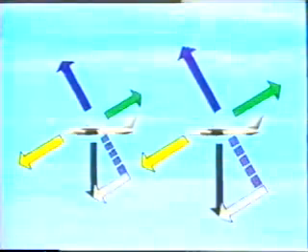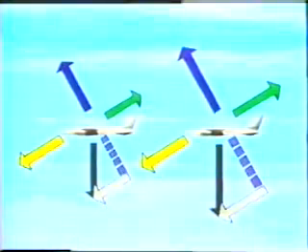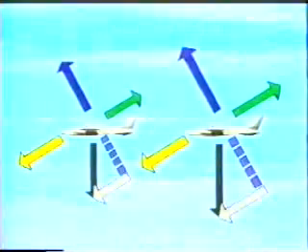Although the heavier airplane goes faster and descends more quickly, the horizontal distance is not affected. From this discussion of LD max, you should be able to correlate what would happen if you attempted to stretch a glide, if it appeared you could not reach the landing area. Although the natural reaction would be to increase back pressure, the increase in angle of attack above LD max would ultimately increase the glide angle and decrease the horizontal glide distance.